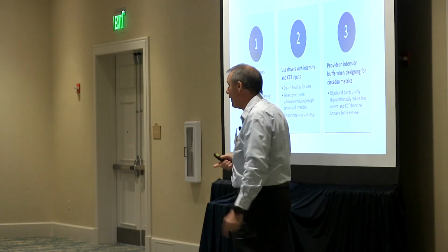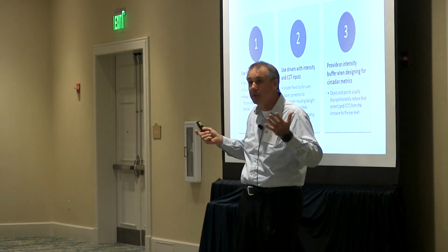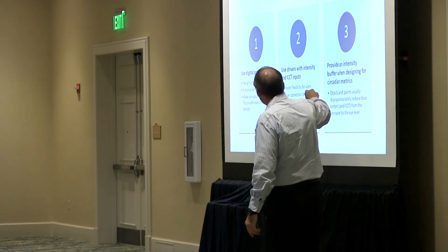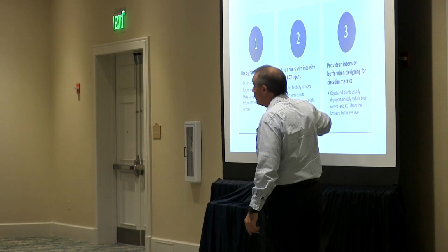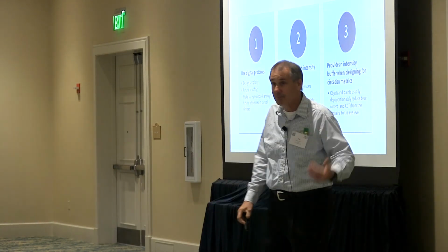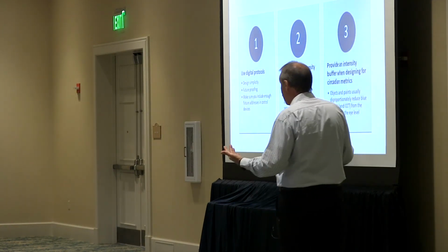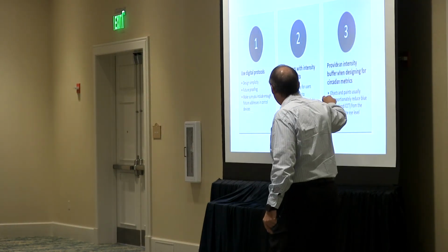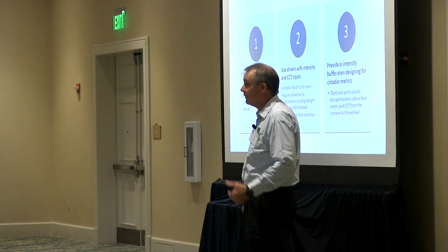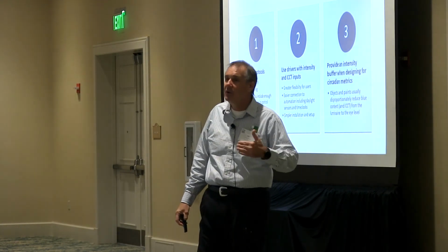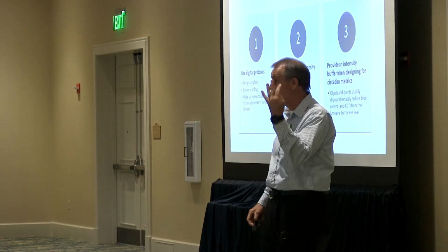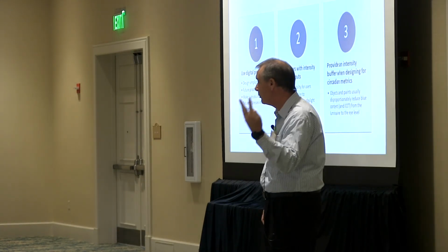So just be aware. I mean, I don't say don't do it, because you will do it, but when you do it, you'll have problems that you can't fix. If you use digital, it future-proofs your design. I can always change the zoning. Whereas 0 to 10, you're going to have to do the wiring. And make sure you include enough addresses to future-proof. If I have to add something or change something, maybe new fixtures will come out with 4 addresses and do really crazy stuff.